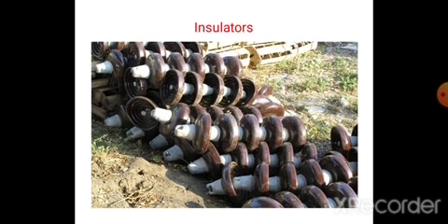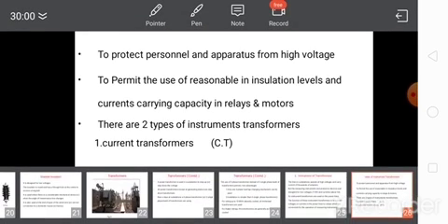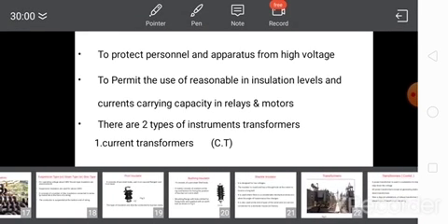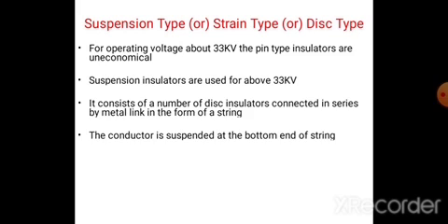This is the suspension type insulator. For operating voltages above 33 kV, the pin type insulators are uneconomical.